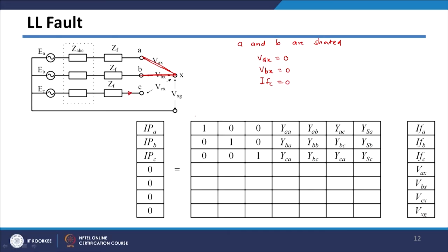And one more equation which we need that I can get: whatever this current IA will be, it will be opposite of IB. So, current IFA plus current IFB should be equal to 0. The addition of both the currents will be 0 at these locations because your IFB is coming from this side and IFA is coming from this side. This should be equal to 0.